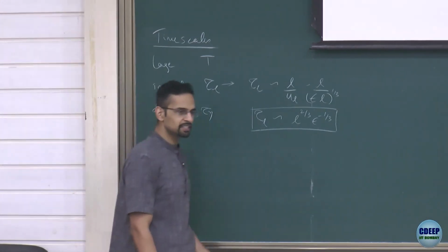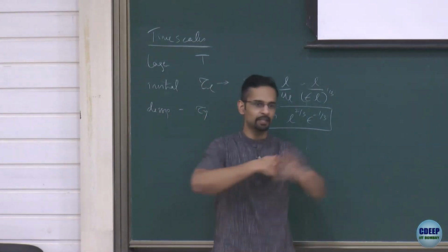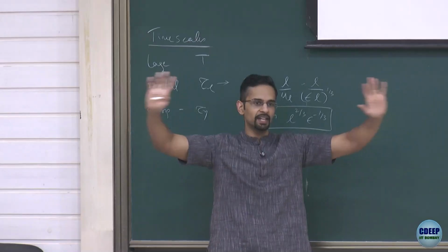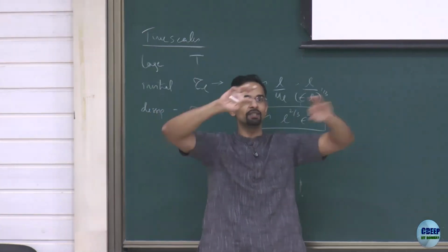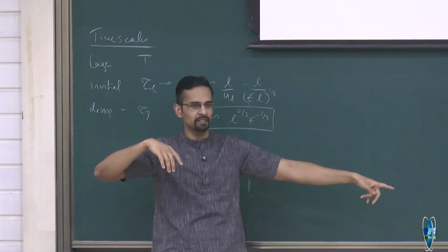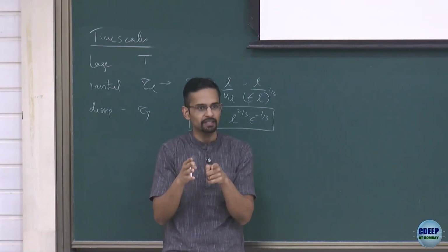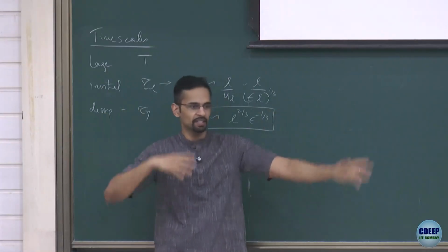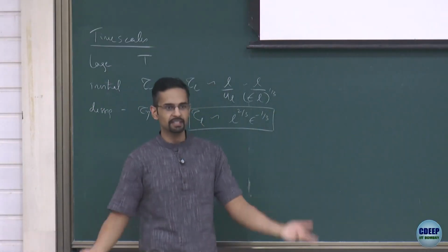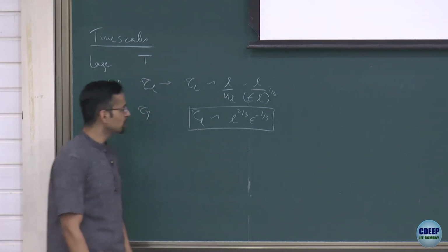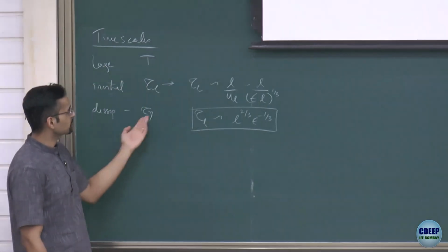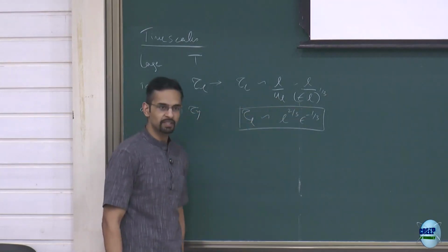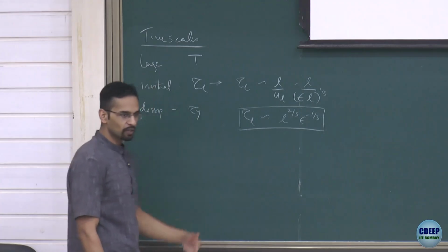Okay, the idea there is that in a turbulent flow, eddies are moving all over the place. So whether I see a still of the single time snapshot of the whole field, and I will see many different eddies by doing an energy spectra, or if I just look at one point and wait for long times, all those different eddies will pass by my point because the flow is behaving randomly, right? And then I'll get the same information in time. So there should be a way to relate, and that's what I've done here, right? I've related the time scales to the velocity scaling behavior in space. So how can we do that with the spectra?